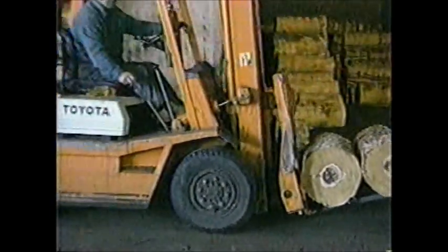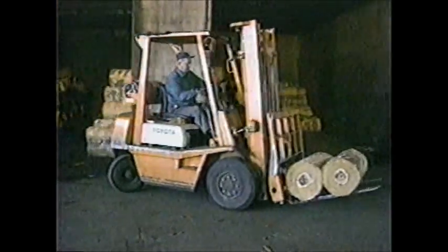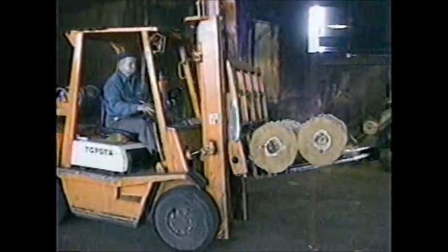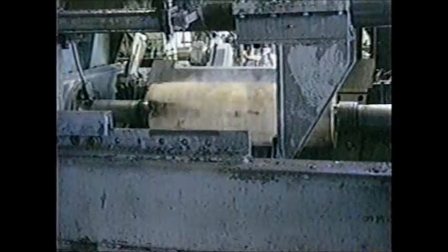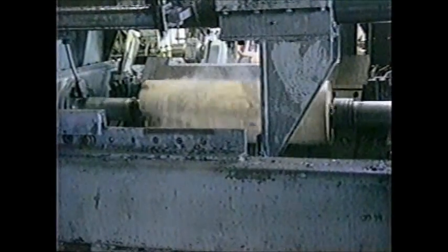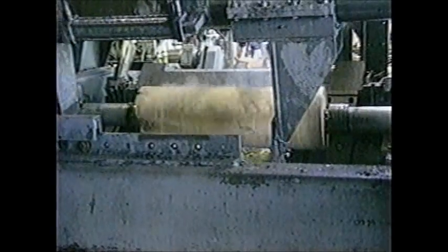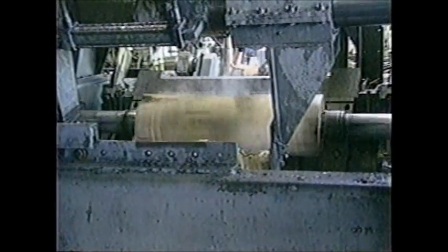Upon entering the mill, the bolts are sorted by length and loaded onto an infeed deck, leading to the lathe charger and rotary lathe. The bolts are transferred from the deck to the lathe chucks by the charger and are turned to a core of about 5 inches.